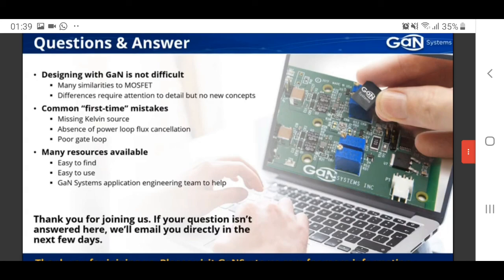On the other hand, if the parasitics are not optimal, usually the designer has to slow down the switching speed. In this scenario, the switching loss will be greatly affected by the increased RG. So the conclusion is yes. If we minimize the stray inductance, we can also minimize the system loss.